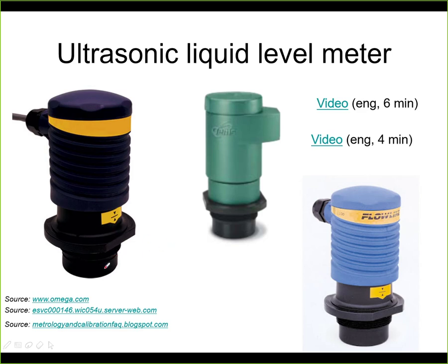And the ultrasound is then projected in a cone, like that. And in the data sheet, you typically find what is the distance or what is the angle of the cone. It's typically very narrow. It's something like 1-2 degrees approximately. So it can be used also in very narrow tanks.